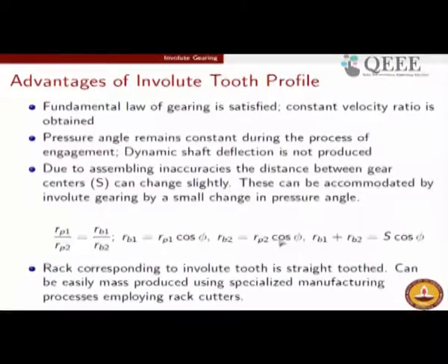This is something similar to what is done in the gear manufacturing process, and you can look up videos on gear manufacturing processes. The Kinematics with Microstation channel has nice videos of gear manufacturing also. We are not going to talk about gear manufacturing in detail in this talk, but suffice it to say that the rack cutter will be the rack associated with an involute gear. There is an involute gear which is supposed to have angular motion. The corresponding rack will also have a certain tooth. It turns out that the tooth corresponding to the involute gear will be a straight tooth.